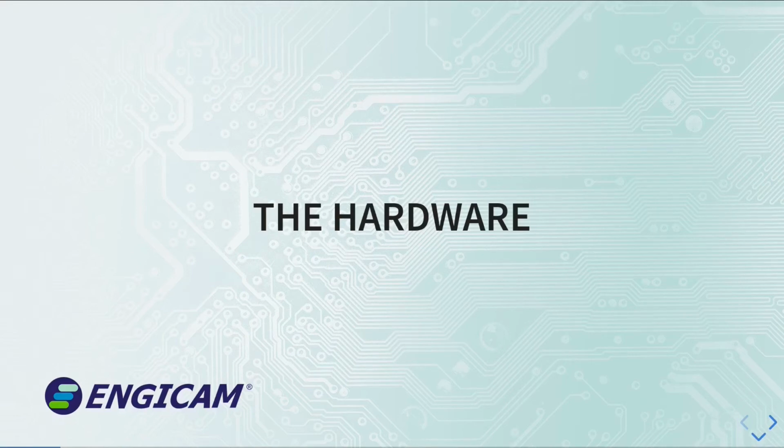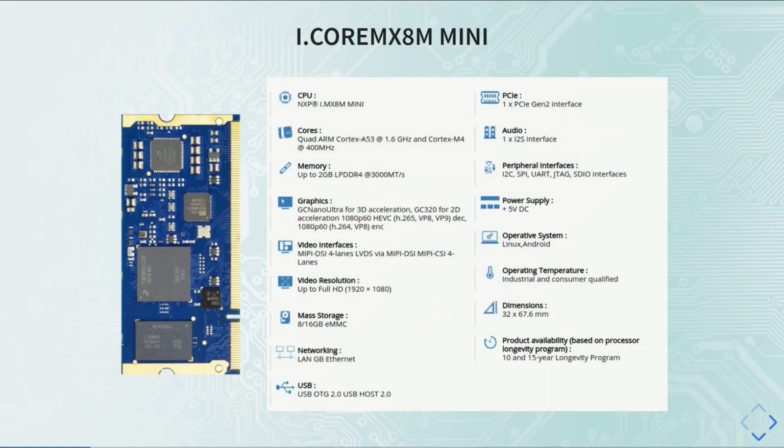Let's start from the hardware. So the Engicam system on module that will be used for this example is the iCore MX8 Mini that is equipped with an NXP processor. Its cores are a quad-core Arm Cortex-A53 and also, for real-time graphical applications, a Cortex-M4. It supports any kind of peripheral and it can run both Linux and Android.